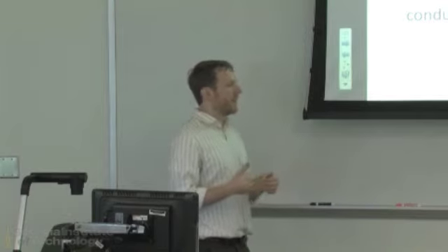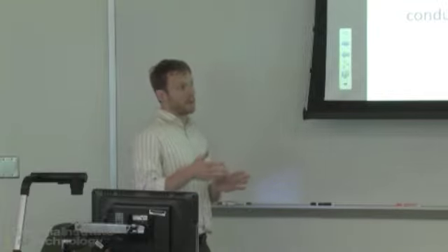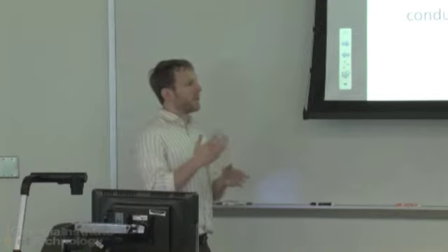The idea is that yes, it will change, but I'm not sure that will actually affect things. We're just using the pump pulse to heat, and the reflectivity is over a very small range. We're only changing the temperature by like 5 or 10 degrees Kelvin. So within that one system, the reflectivity might be different, but we're not making an absolute measurement. This is just a relative measurement of the change in temperature.